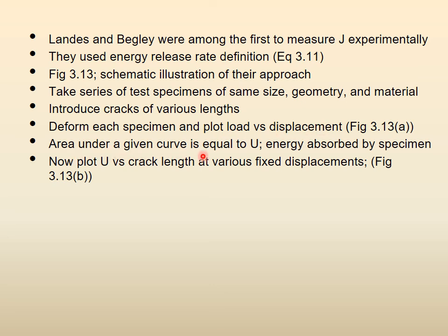The area under a given curve is equal to the energy U, the energy absorbed by the specimen. So they do load versus displacement, and then the area under the curve is U. Then they plot U against the crack length for various fixed displacements. We will just show you the figure and it will become easier.